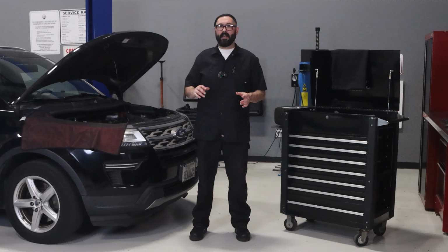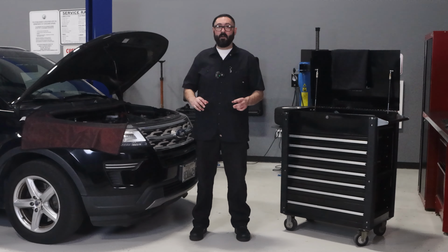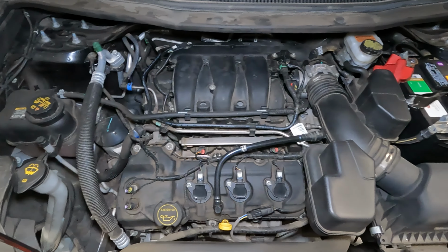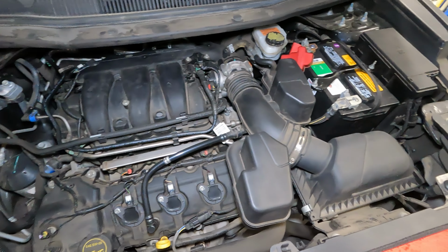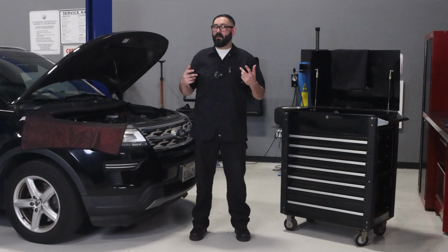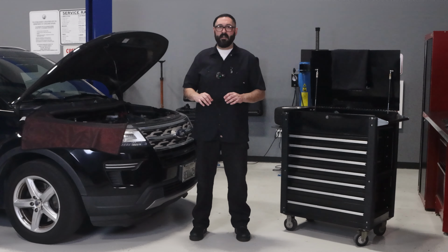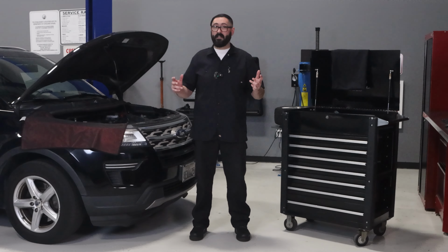Now, before getting into diagnostics, always start with a full inspection of the vehicle. Document symptoms and background information. This is going to include when the issue first started, what the driver noticed, were there any previous repairs, what were the driving conditions when the problem happened, were there any warning lights, smells, strange noises. All this information is going to help you prepare your diagnostic strategy and help you save your time down the line.